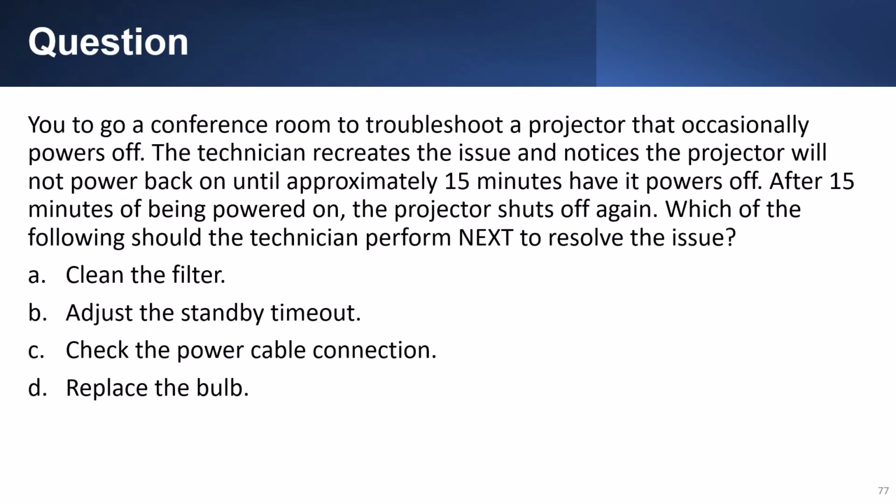Question: you go to a conference room to troubleshoot a projector that occasionally powers off. The technician recreates the issue and notices the projector will not power back on until approximately 15 minutes after it powers off. After 15 minutes of being powered on, the projector shuts off again. Which of the following should the technician perform next to resolve the issue? Answer: clean the filter.